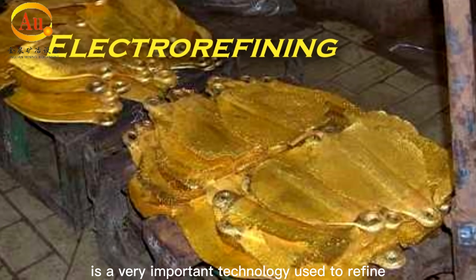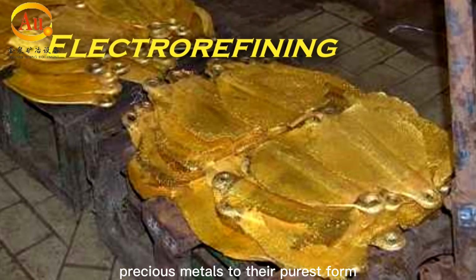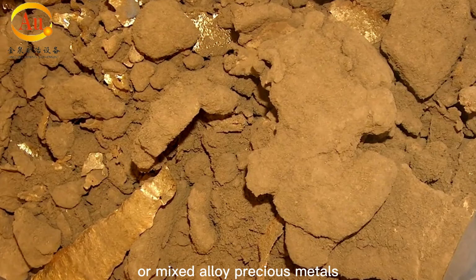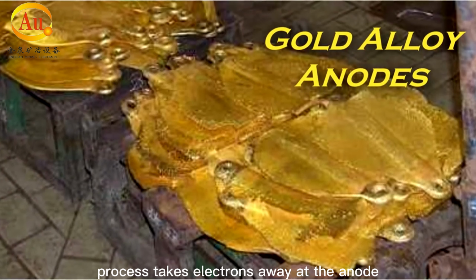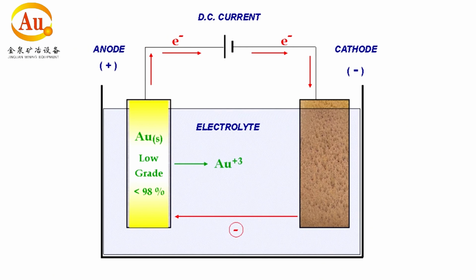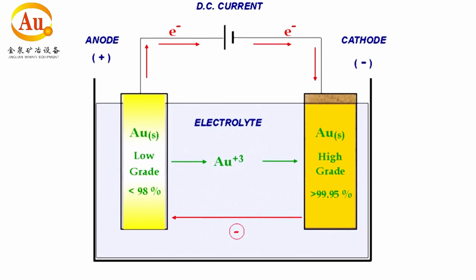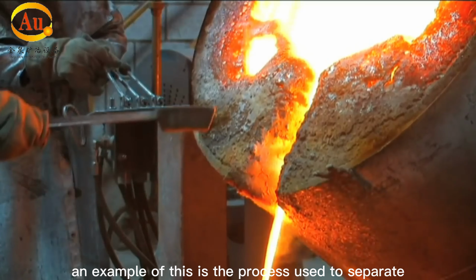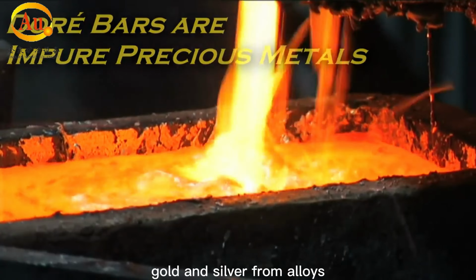Electrorefining is a very important technology used to refine precious metals to their purest form. Whereas electrowinning takes metals from leach solutions, electrorefining starts with anodes made of low-grade or mixed alloy precious metals. The electrolytic process takes electrons away at the anode, which dissolves the positively charged metal ions into solution. These ions are then selectively plated out of solution by adding back the electrons at the cathode. Fine-tuned chemistry of solutions and electrical currents are utilized to separate or part precious metals from each other. An example of this is the process used to separate gold and silver from alloys.